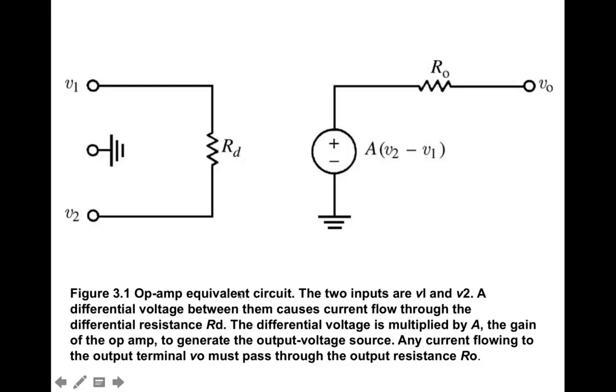So that's an ideal op-amp, and generally, the other thing is that op-amps have to have external power supplied. As a general rule, if the op-amp voltage exceeds the external power supply, then you're no longer in a linear range. So for first order approximations of how op-amps behave, we usually assume we have an ideal or close to ideal op-amp, and we also assume that we're operating in the linear range. If not, then we have to model these components of the input impedance, the non-infinite gain, and the output impedance.